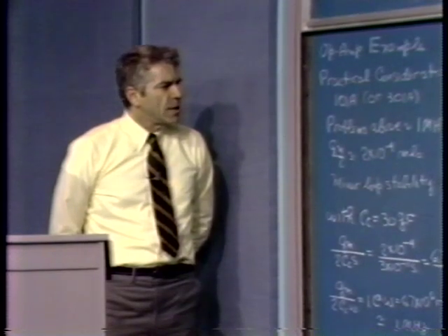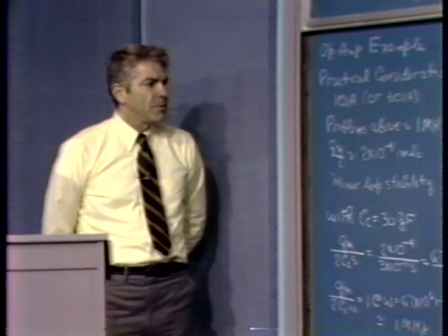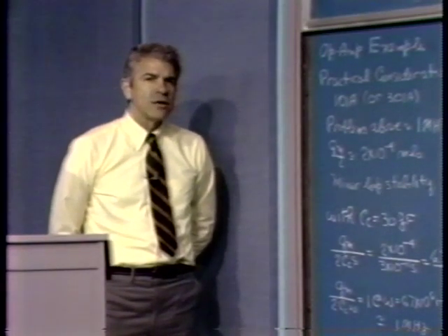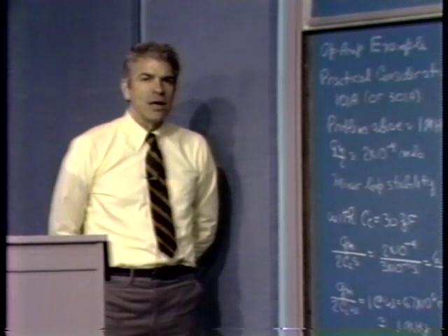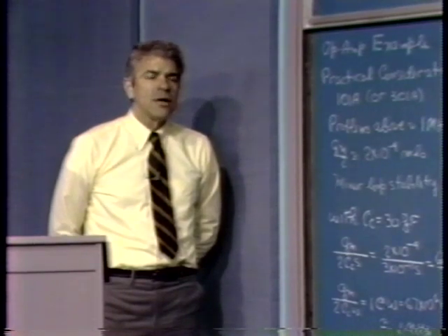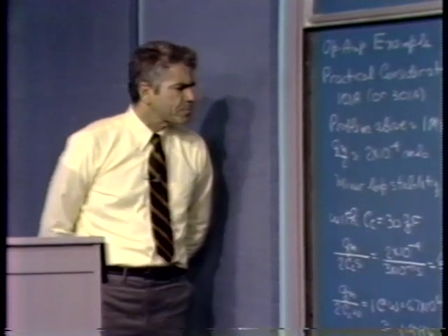So we have to bear in mind when we're doing our compensation that for any loop that includes this kind of an amplifier, the major loop crossover is constrained to somewhere on the order of a megahertz. Actually, that's been getting a little bit better with time, reflecting process improvements. We'll see in the amplifier we're using now, we can get about 2 megahertz crossovers without too much trouble.